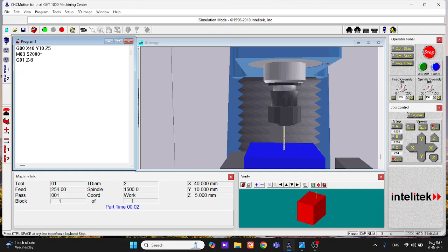And what is the feed rate? Feed rate is the movement of the axes in millimeters per minute. So I will make it 200, which is up to you. I don't want to make it fast, in order for us to see the movements of this tool. So now it's ready. After I set the run, now that we are in position, it will start from here, the spindle will be turned on, and then it goes deep with this feed rate, ready to move to the next coordinate. So what is the next coordinate?